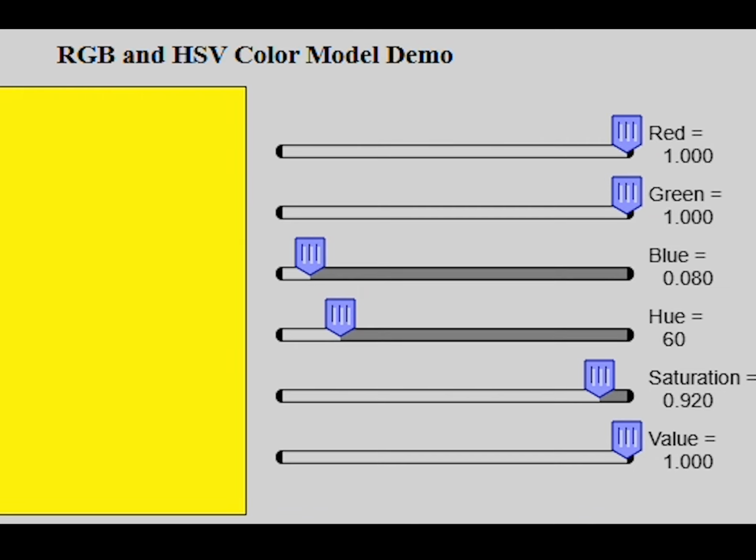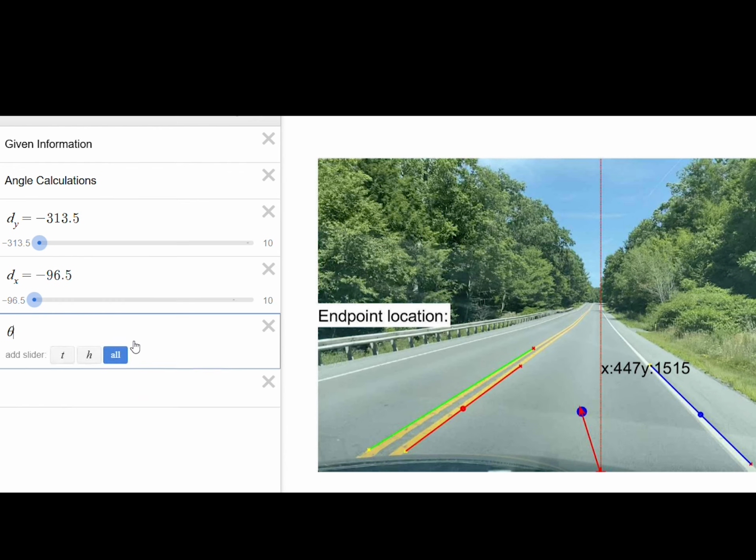Having developed an image filter, our team calculated heading angles to inform the robot's steering. To determine the heading angle, we used inputs from the camera to determine how far offset the center of the image is from where the robot is looking to the line on the road.